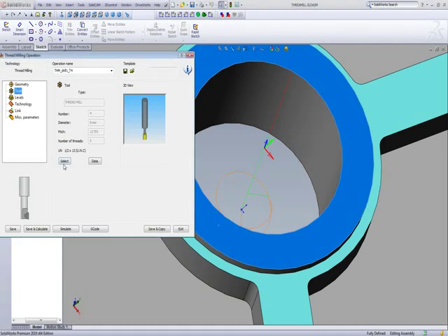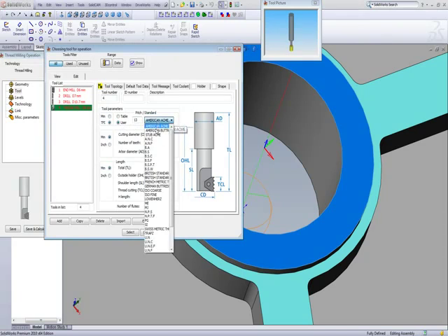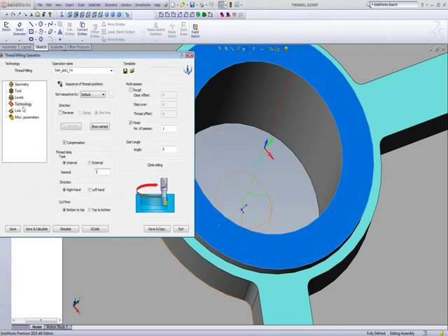Now let's go back into our tool. We had defined our tool by using a table. We can also define the tool by the user. When I choose the option of user, then we put in all of the information that we need. We can pick what standard we want to use. For example, I can use the UNC standard, and all the information is open for me to put in as I wish. I can put in any value I want here, whether it be 13 threads per inch or 12 or 10, whatever value I want. All of these values are put in by the user. When choosing this as my option for creating a tool, the value in the technology of the thread data will be 0, and this is again something that is put in by the user. This also allows you to do special threading as well.